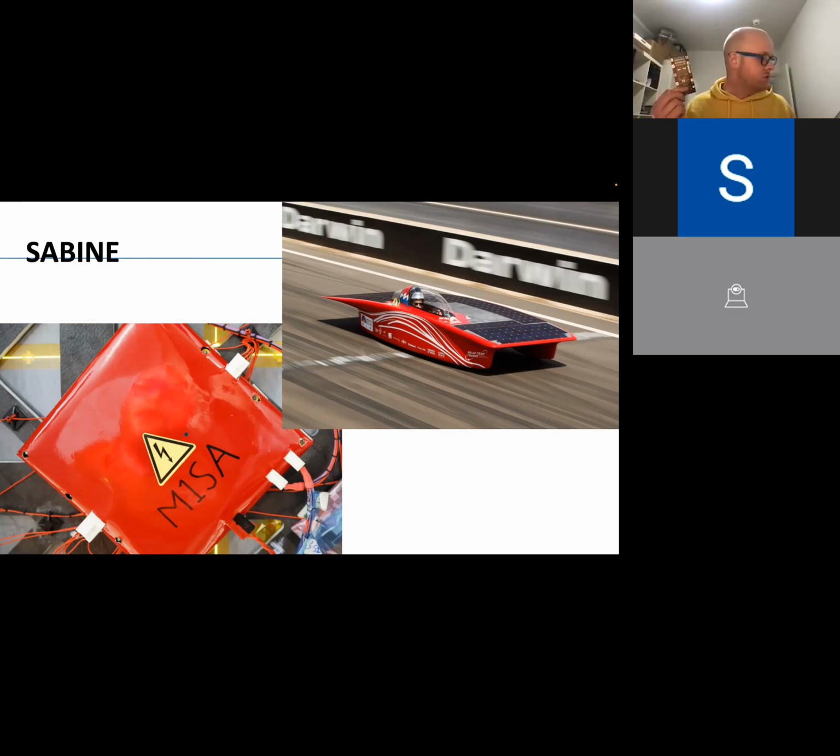Well, the ones that you use for your batteries are usually optimized for measuring voltages around 3.7 volt. So what you do is you put 6 solar cells in series, and then you call that one group. You don't do it per solar cell, right? You still make groups, but you make them a little bit smaller, and then you're able to measure the voltage of every 6 solar cells that are placed in series.